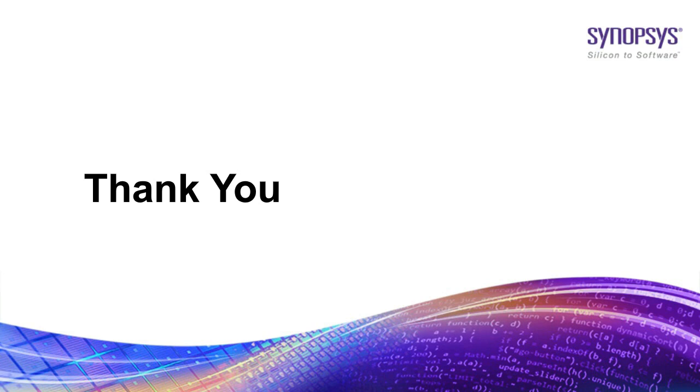Now, in terms of patterns, we do also have different IEEE standards that we are utilizing to describe the patterns. CTL and STIL have been used by us for a long time. We continue using those for logic blocks, and at the top level, PDL and ICL, which came with 1687. They're very good to describe the hierarchical level test of the different IPs. So you go there and you choose which IP you want to run, and you have the PDL of that IP to execute. And ICL gives you the infrastructure to approach that.